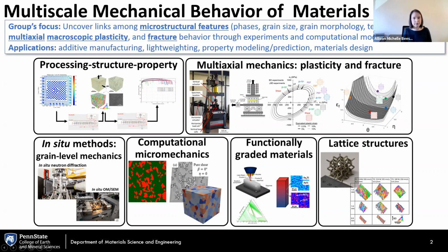And then some of the areas that we're also interested in terms of additive manufacturing are shown here, just for completeness. So functionally graded materials, where we use directed energy deposition additive manufacturing, where you spray the powder into the melt pool to build up your component. And by varying the composition of what we deposit locally, we can then have gradients in composition and therefore gradients in phases and therefore gradients in properties. So this is work that we've done with Zikui Liu over the past few years.